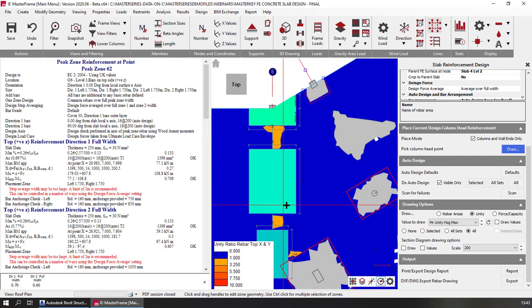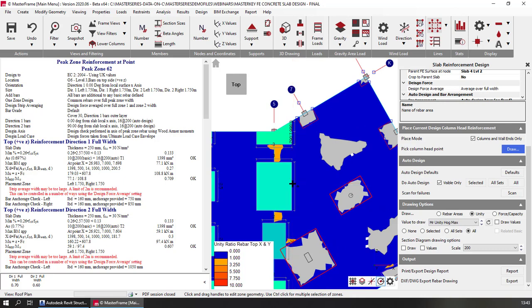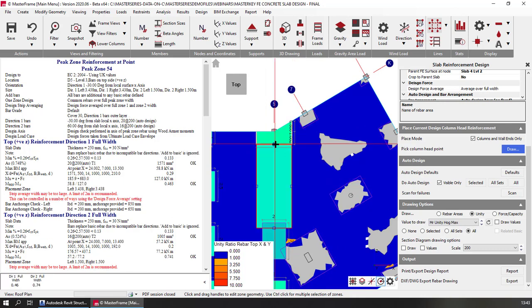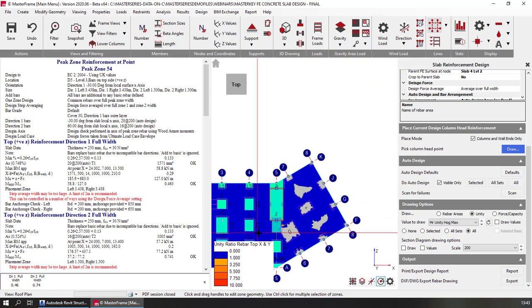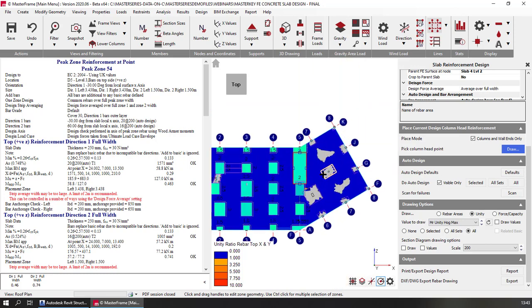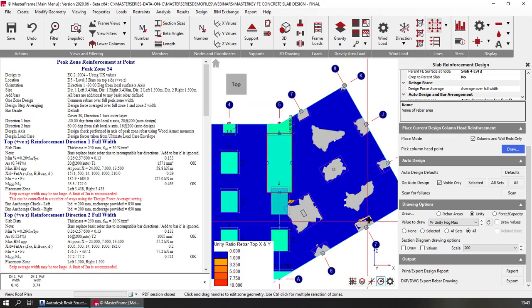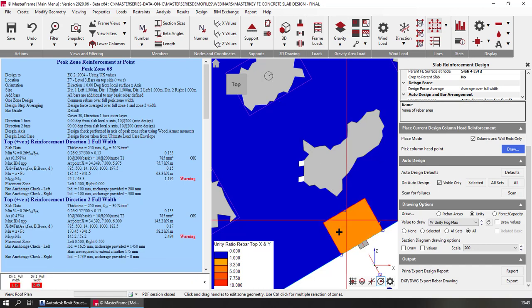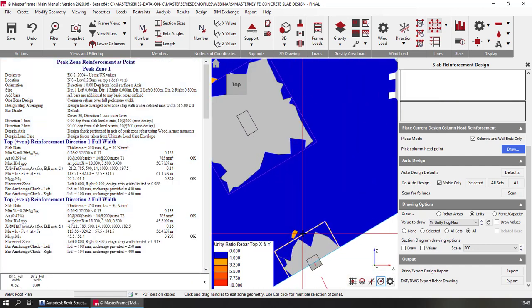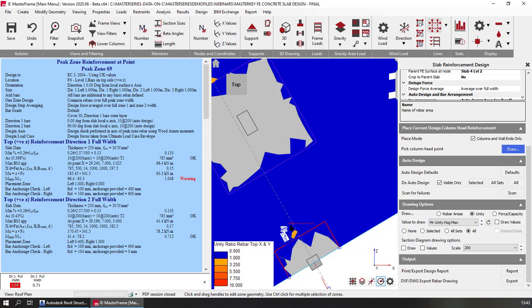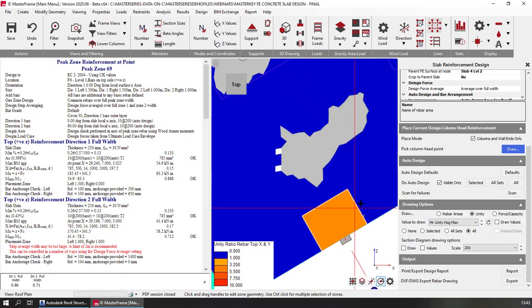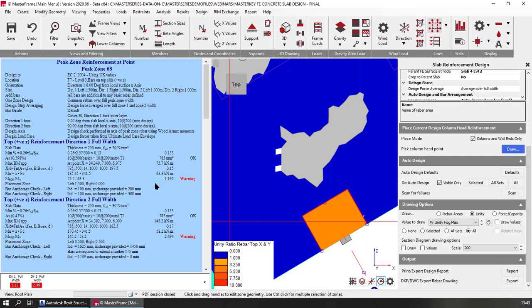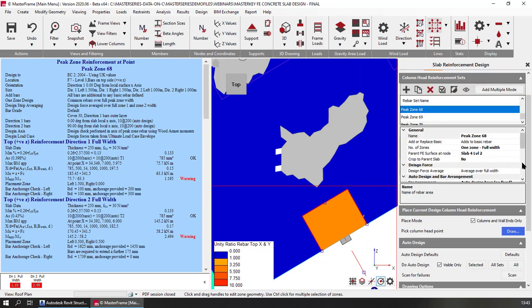Now we are still getting this over here and here, so you might take the attitude of saying, well, let's just take that right out to there and have that over there, and we'll actually end up using this heavier reinforcement here rather than this, and that's us done. And over here we've got the tiniest of overlaps, and this is where the 30 degrees tracking is very useful. It allows us to draw these a lot more accurately. And this one appears to be slightly unhappy. We just need to put bigger rebar in.